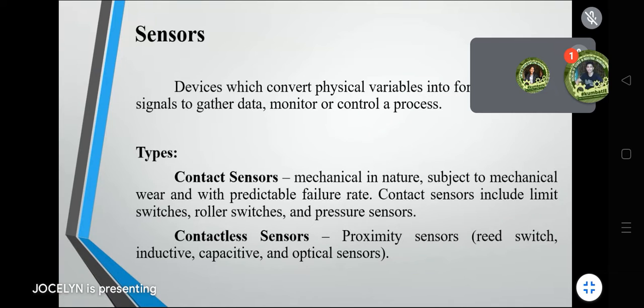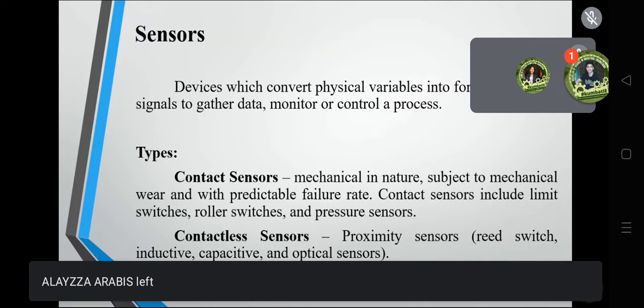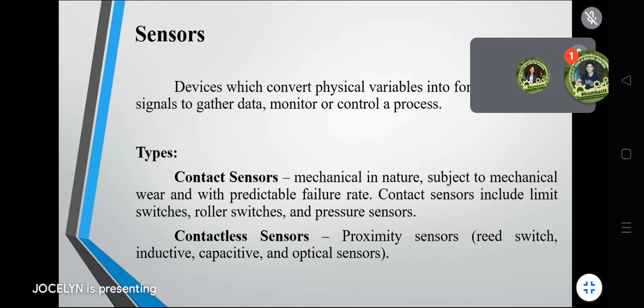That means we can attach a pressure sensor at the bottom part to detect if the pressure is high, meaning there is little water, and we can also attach a pressure sensor on the upper part. If there is less pressure, that means there is a lot of water already. Once the pressure is high, meaning less water in the tank, we can connect a buzzer for an alarm.